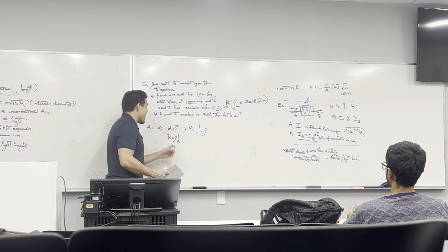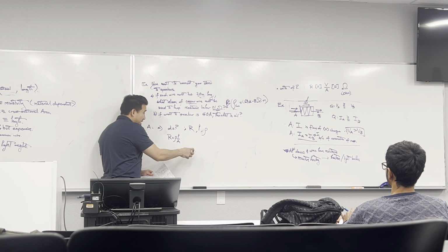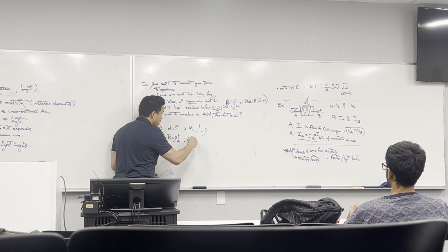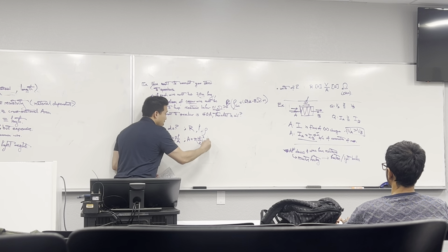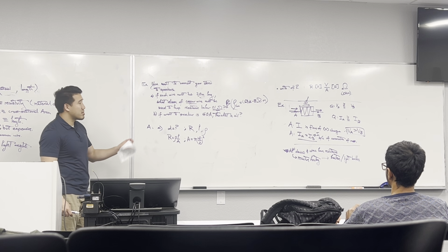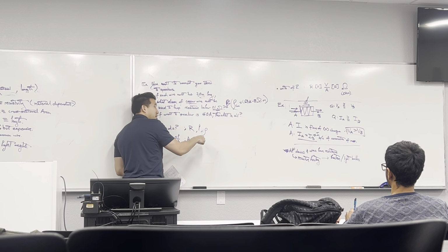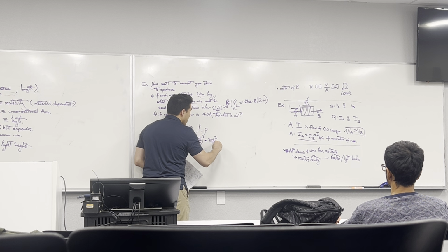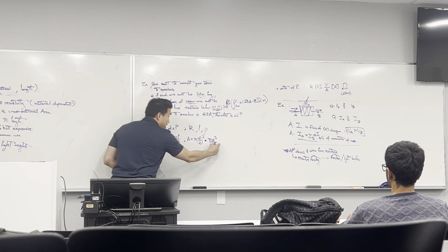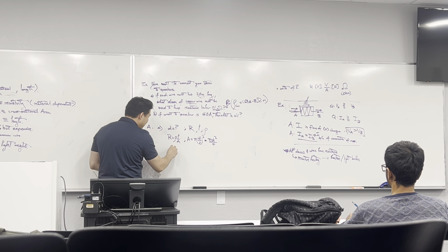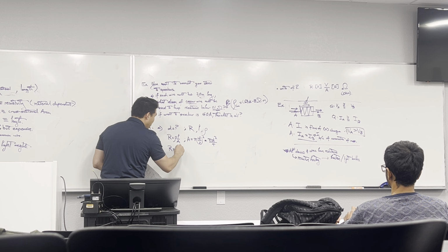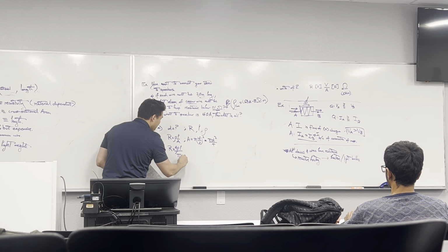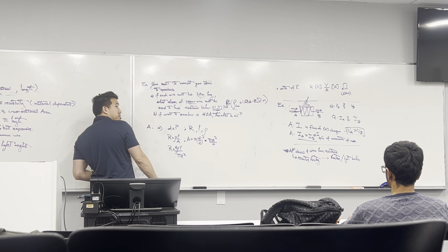And further looking, we know that A, the cross-sectional area, is going to be pi times d over 2 squared. Right, pi r squared. And radius is diameter divided by 2, or simply pi d squared over 4. So if we were to put this in for our A, then we would get R is equal to rho L times 4 over pi d squared.